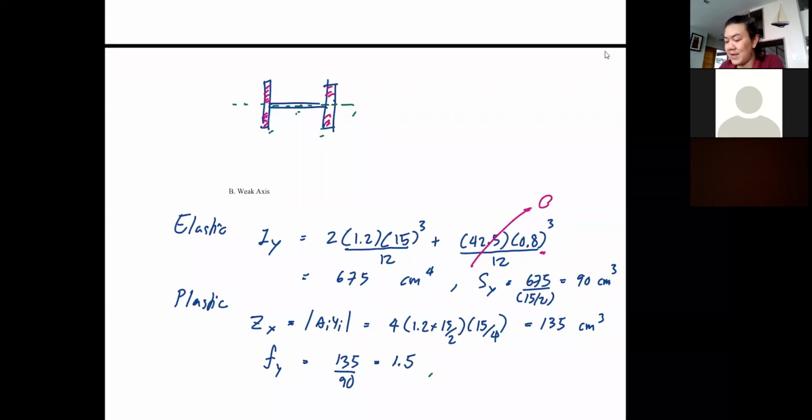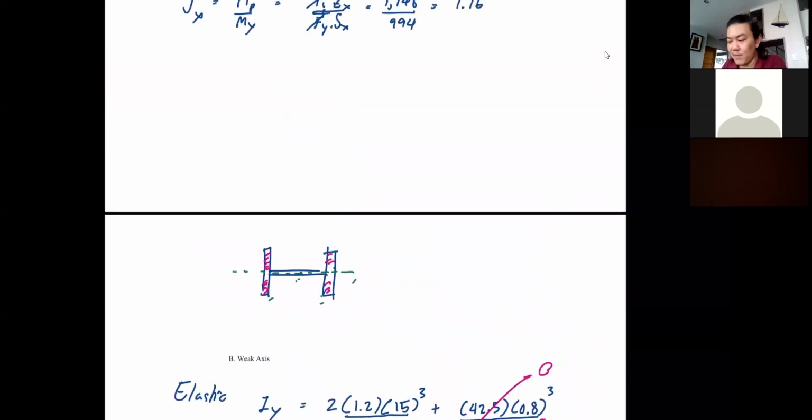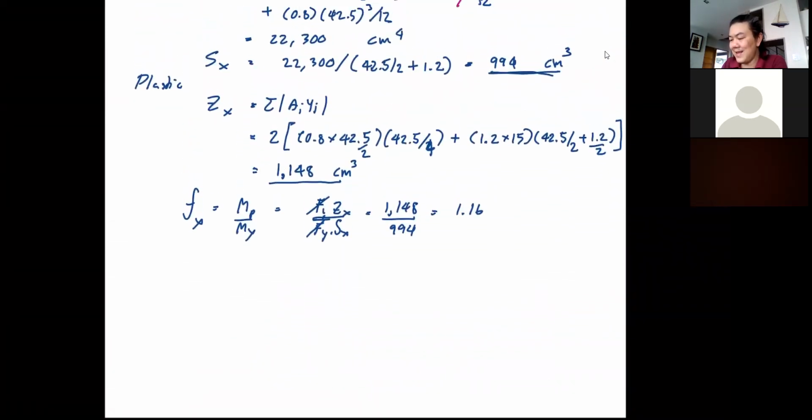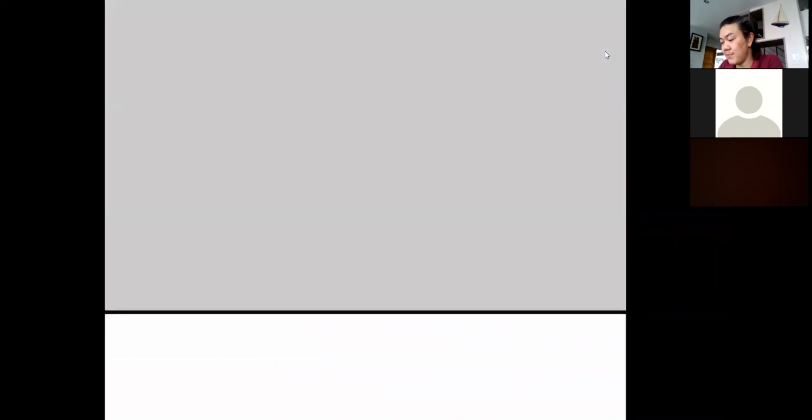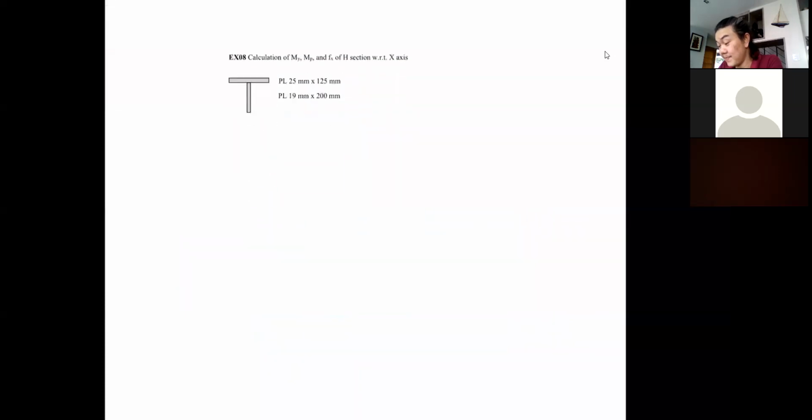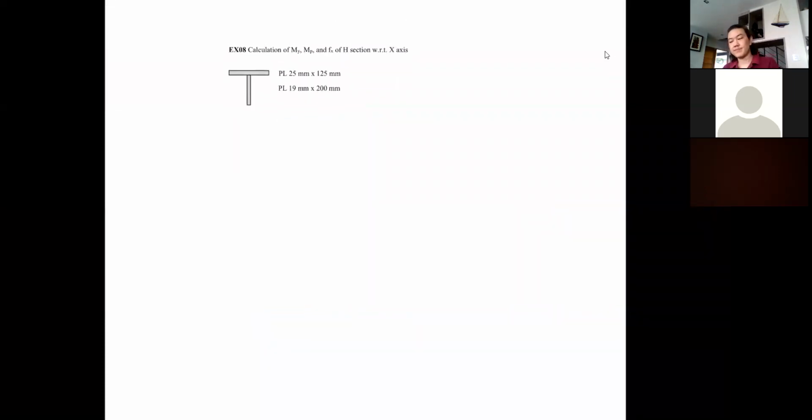But keep in mind that even though we got a large shape factor here, the plastic and elastic section moduli, it's a plural form, right, are quite less than what we have from the major axis. So that should clear this up. And now I am left with just another example to demonstrate another problem. Now this one, just the x-axis will be enough. Now you need to locate the centroid, right?